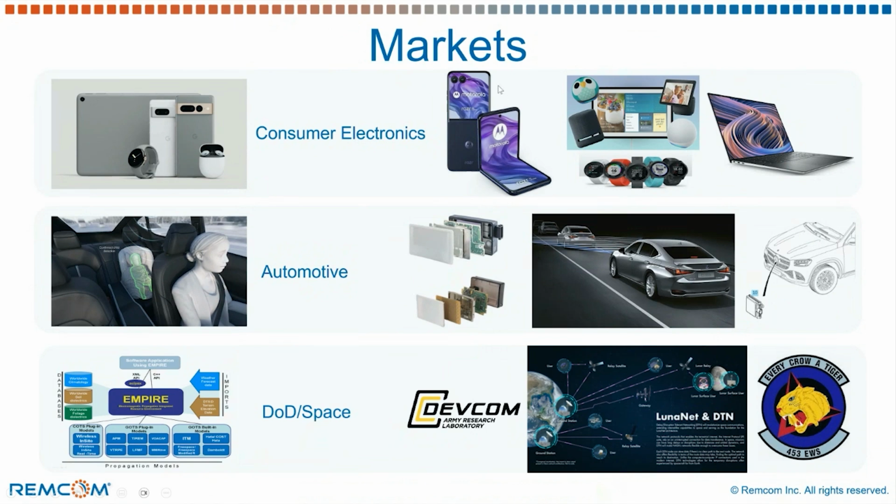The challenges in consumer electronic spaces include the reliance on matching and circuit matching, with the synthesis of the matching network to tune and match antennas, numerous antennas, about 8 or more. And these antennas require isolation, they require exposure studies, and they require the correct component values to be able to tune and match for specific bands, potentially in the 30 to 50 5G bands. Doing that inside XFdtd with the circuit schematic functionality is extremely powerful.